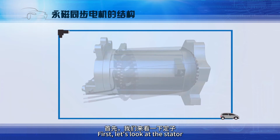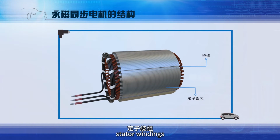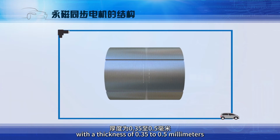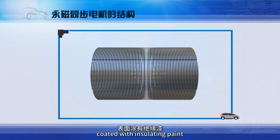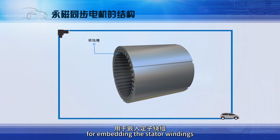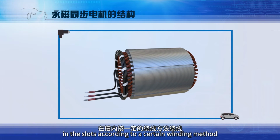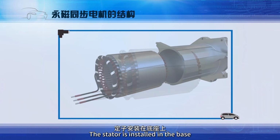First, let's look at the stator. The stator consists of a stator core, stator windings, and base. The stator core is usually made of silicon steel sheets with a thickness of 0.35 to 0.5 millimeters, coated with insulating paint. The inner circumference of the core is filled with uniformly distributed slots for embedding the stator windings. The three-phase windings are embedded in the slots according to a certain winding method. The stator is installed in the base.